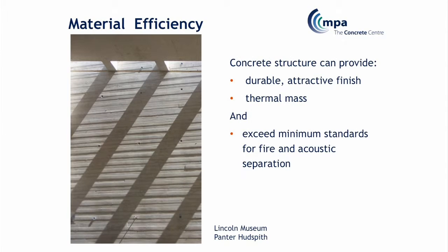Of course, the other aspect of concrete, thinking about the whole process holistically, is that it's incredibly material efficient. If you take a concrete wall that is providing you with your structure, it's a durable, low maintenance solution, but it's also probably going to exceed those minimum standards that you need for fire separation, for acoustic separation, as well as providing you with some thermal mass benefits.